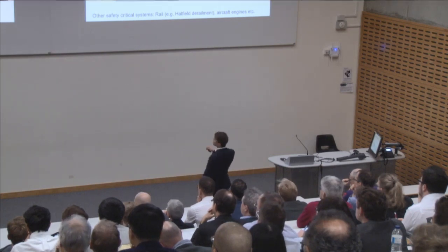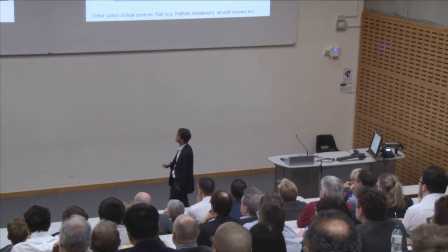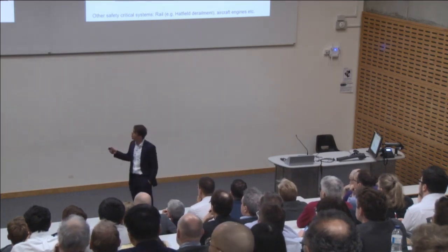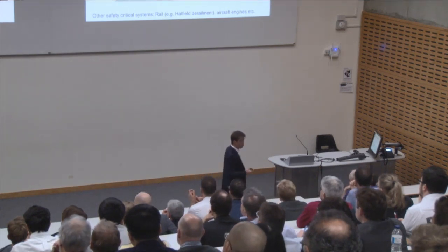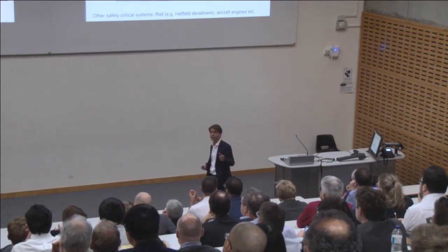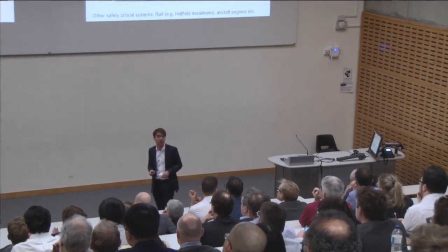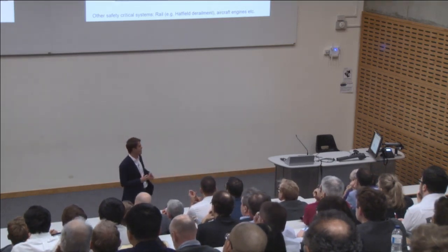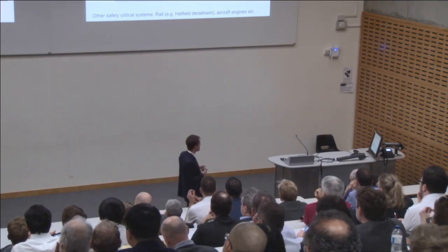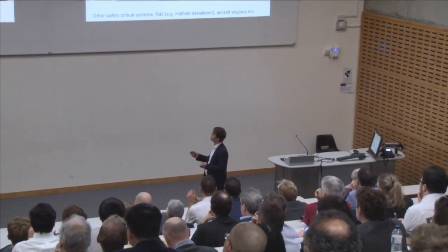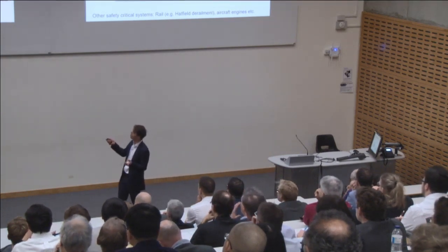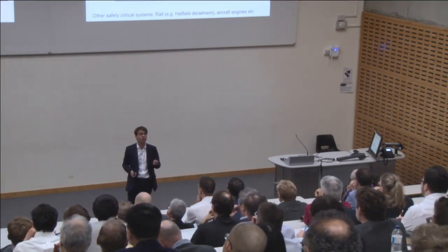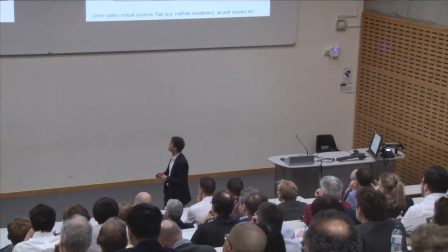It's under what they call a Creative Commons Attribution License, so you can look at it and share it, where the Super Puma that crashed in Norway in 2016 was found to crash due to rolling contact fatigue failure on the planet gears in the main gearbox of the helicopter. As an ex-colleague of mine, Andy Olver, used to say, a helicopter is just a flying gearbox. There you see one of the cracks in the planet gear from that video, and you will see later on in some of our research we generate something that looks very, very similar to this.